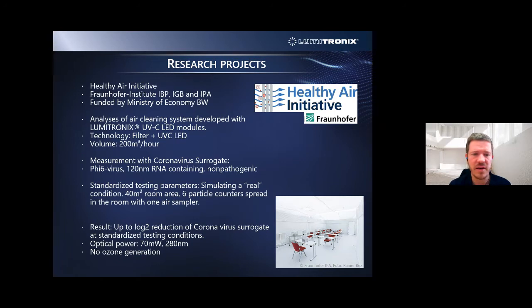Our results with our air cleaning system show up to a log2 reduction of this coronavirus surrogate at standardized testing conditions, which is a pretty good result in our opinion, because we are only putting in an optical power of 70 milliwatts at 280 nanometers at the moment. There is, of course, no ozone generation included in this test.